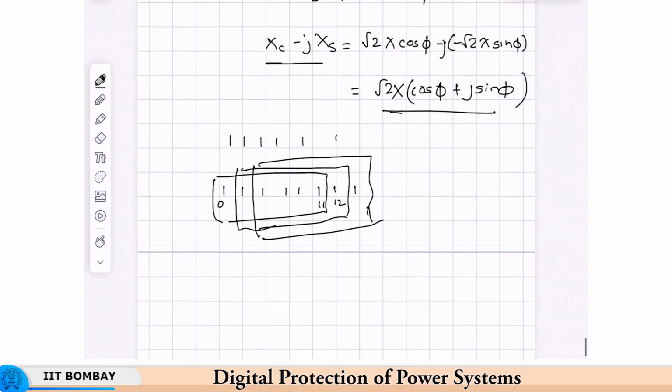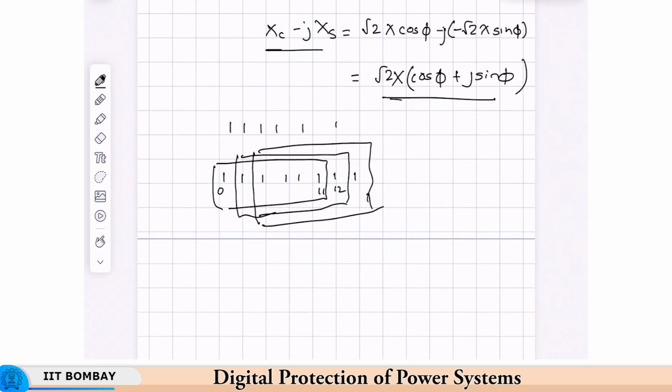Okay. So, windows can be numbered. We need to know that window number to calculate the DFT. The windows can be numbered with the first sample in the window or with the last sample in the window. These are the two conventions that can be followed.